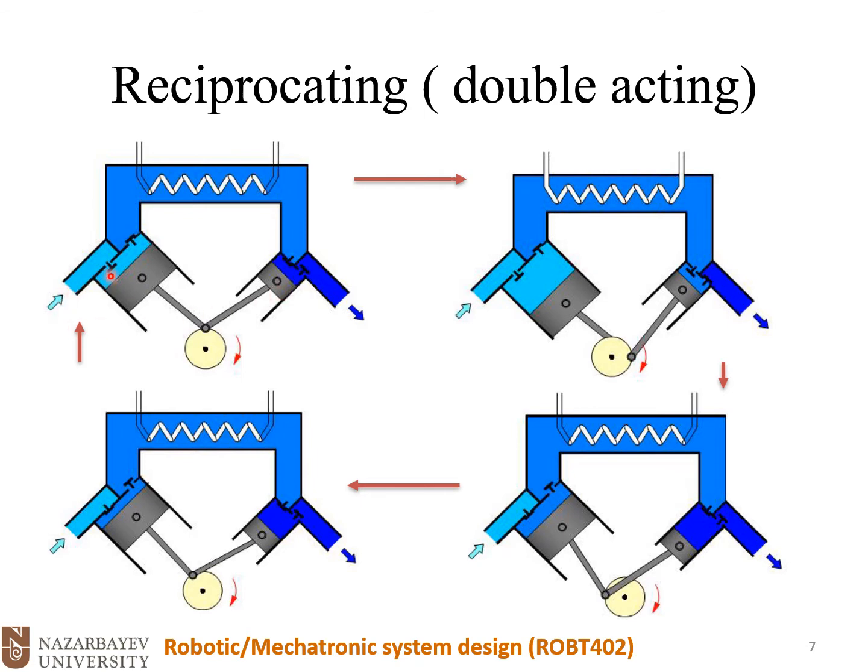So at the first stage, the first cylinder will suck the air into the chamber. So we have air here now, and now the air will be compressed. The air will be compressed by moving the piston, decreasing the volume, and now we have a high pressure air. So look at these valves.